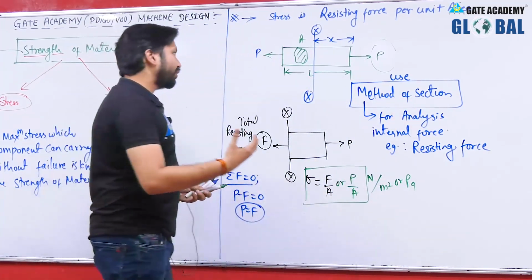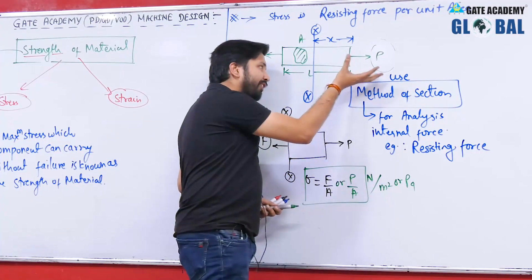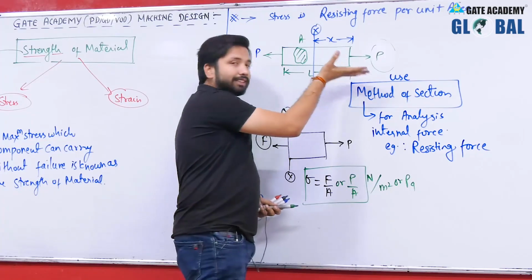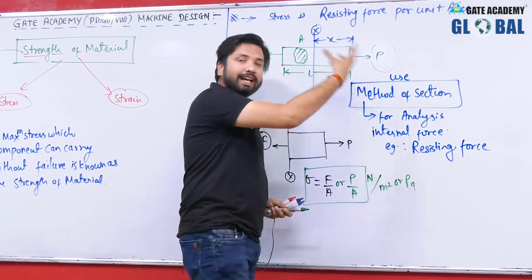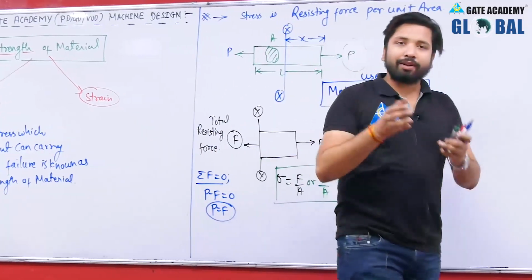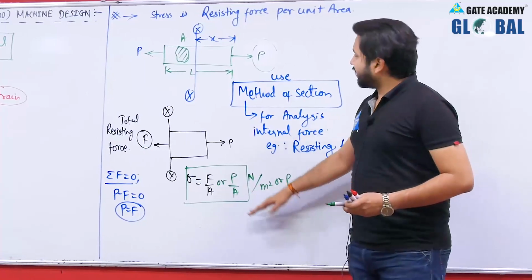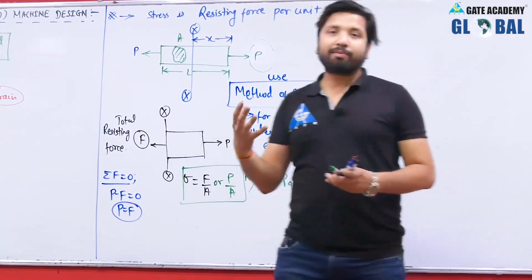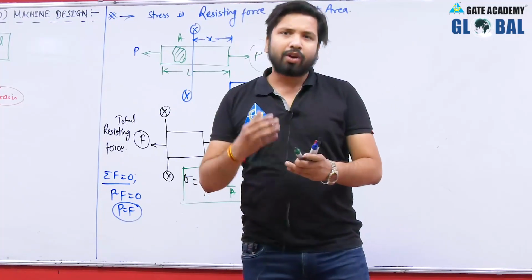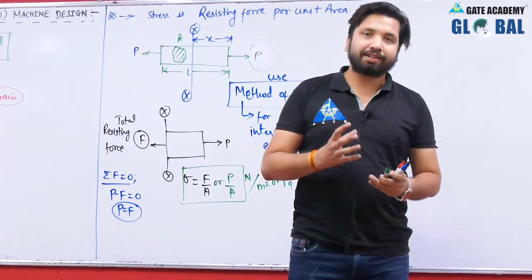Now as I have told you, if a component is subjected to an external load, then the fundamental nature of the load, that is a force, is to deform the body, that means to change the shape and size of the body, hence there will be a deformation as well. So along with stress there will also be a deformation. Now we will be measuring the deformation in terms of strain. Now what is strain? Strain is deformation per unit original dimension.